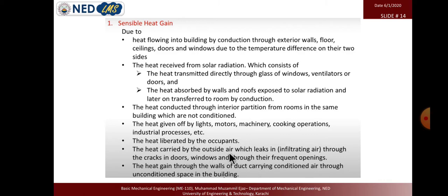So when the door opens, outside air comes inside the room. So we have leaks and infiltration through the cracks in doors and windows, the frequent opening of doors, etc. I already gave an example. The heat given through the walls of ducts carrying conditioned air through unconditioned spaces in the building. So all these are factors that produce sensible heat in the room. Okay.